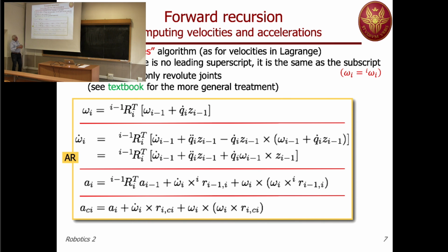Now, you should take the derivative further, but if you remember that we are dealing with a vector expressed in a moving frame, then there will be an extra contribution coming from here, because this is a unit vector. So it doesn't change intensity, but it rotates with the frame. So we know that it will generate also a cross product of the angular velocity that we are having, so omega_{i-1} vector, the cross vector, the same vector z_{i-1} here. And everything is pre-multiplied by q_i dot.